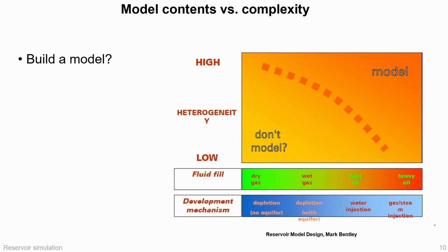If the reservoir has low heterogeneity, simple fluid behavior, and simple depletion, sometimes analytical methods may be enough. But when heterogeneity increases, when fluids move from dry gas to heavy oil, or when development moves from natural depletion to water or gas or steam injection, simulation becomes much more necessary.